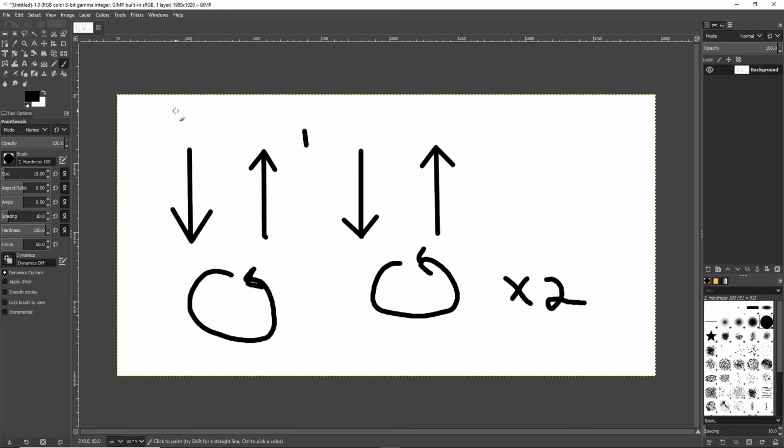However, up here, I only want this intake valve to open on this one stroke. So if this camshaft rotates at the same time this crankshaft rotates, it would open here and open here, and that's not going to work. So for every full cycle, the crankshaft will rotate twice, but the camshaft will only rotate once.